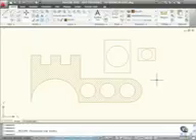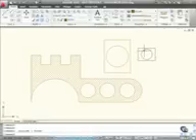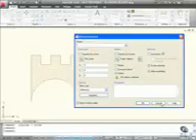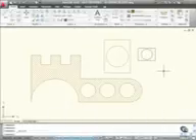One final way though, select the block, I can now explode that, takes it all back to layer 0, I can perhaps make a new block, and then go Block Create up here, and select those objects to make a new block once I've exploded an original block.